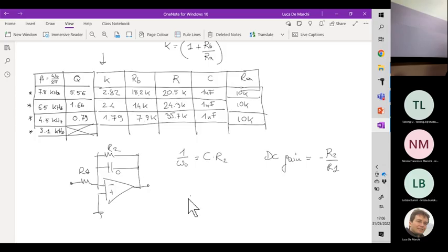If you multiply the gain of the first stage times the gain of the second stage times the gain of the third stage, what you get should be around 11.66 volt over volt, while the total DC gain you want is equal to 10. So this is first, second, and third: K1, K2, and K3.